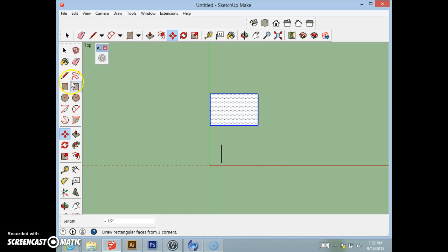Let's say I'm going to copy this object. And right now this is just a bunch of selected faces and edges. It's not a component yet. We'll look at turning this into a component in a second, but components are real interesting to work with too. The good thing about components is they're grouped. Right now this object that I'm working with is not grouped. So if I were to put it with something else, it would not be very easy to move it apart.